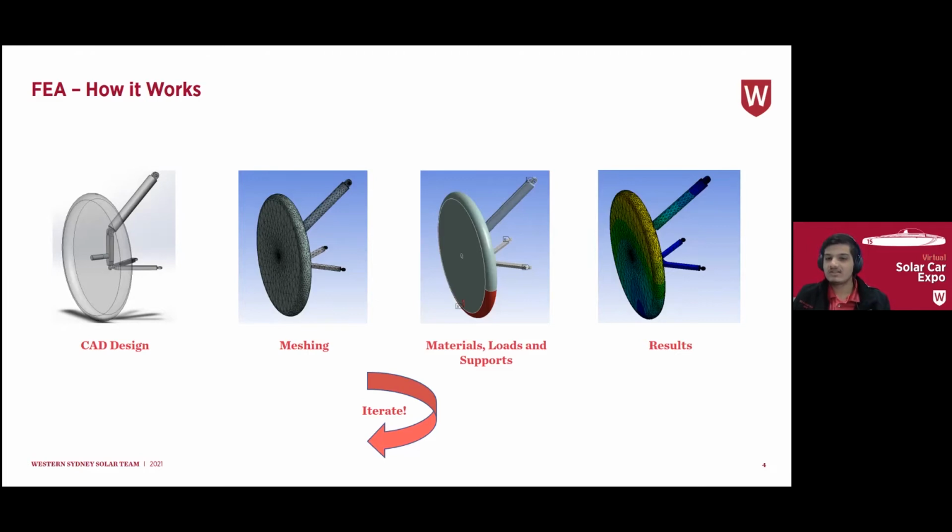Based on these conditions, the simulation results can output various parameters that describe the behavior of the part. The main ones we look at are the stress distribution and strain, deformation, and factor of safety outputs. The amazing part of this software is that it is displayed as a 3D color graph that's overlaid on the part itself. This allows a more visual understanding of weak points and over-engineered sections. Using this, you can add material where it's needed and remove it where it's not.